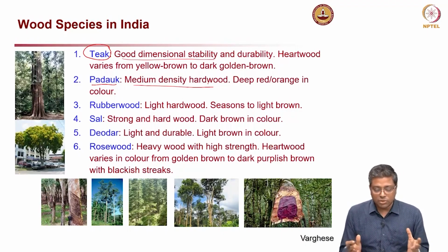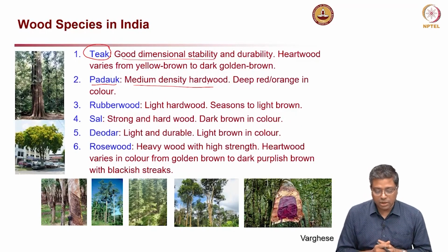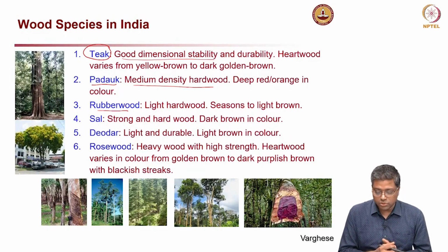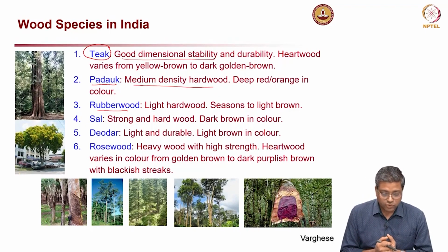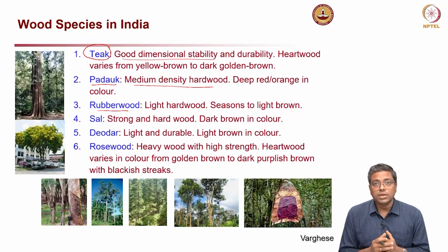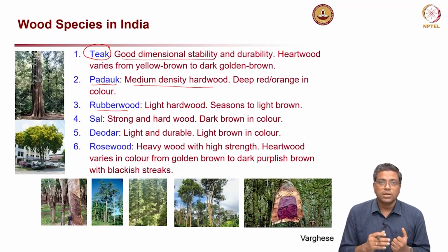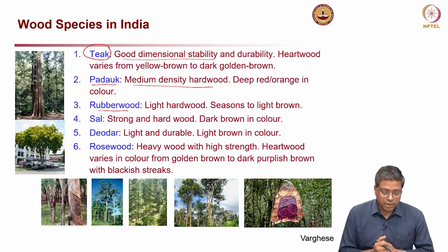This is not something to memorize, it's just for you to have a feel of what types of timber or wood are available in our country. And what are the properties you should look for? Color is definitely one thing, because aesthetics is something we look for, and also the dimensional stability, strength, and how easy it is to work with that timber. These things we should really worry about.